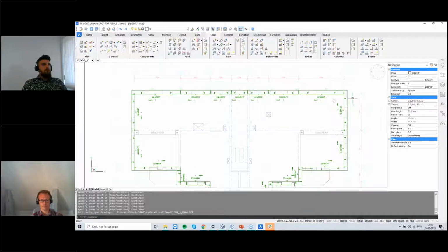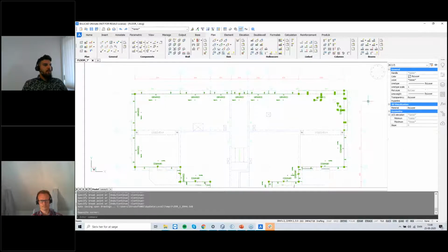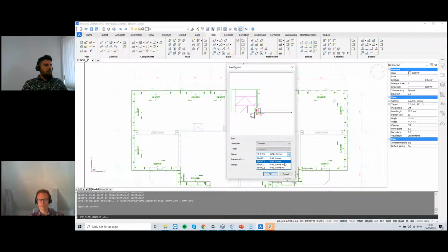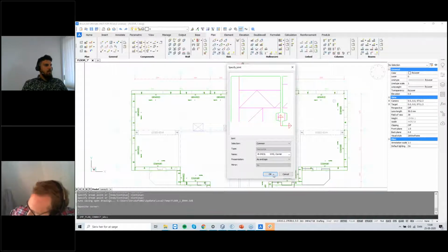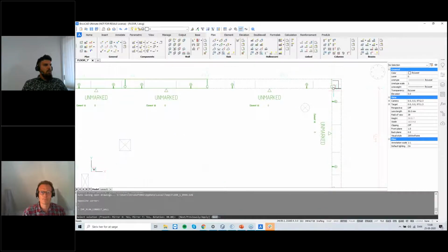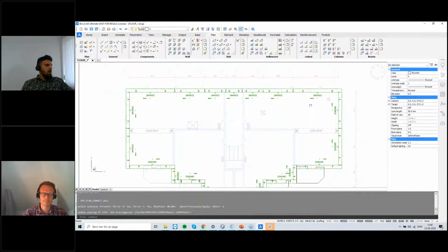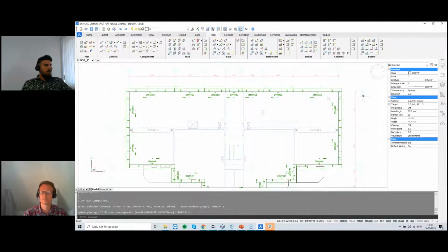But due to many options and many things that you can do in the design, I can select those two walls, press this function called connect wall, and basically apply the new joint onto my walls. A joint like that, which is basically the same as this joint. And when I say OK, I can start working around and making apply, update all. And now I have the edge from my left side looking like the one on the right side.